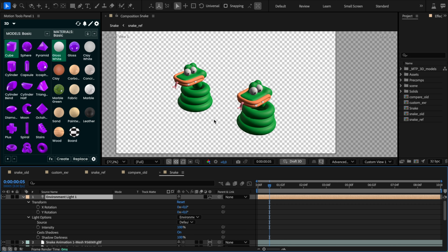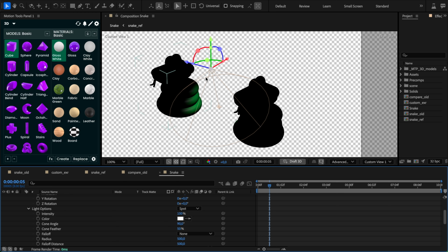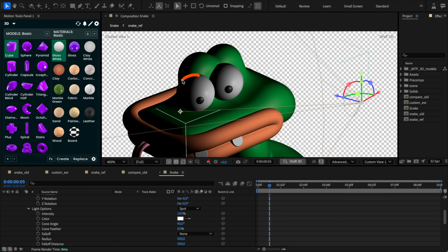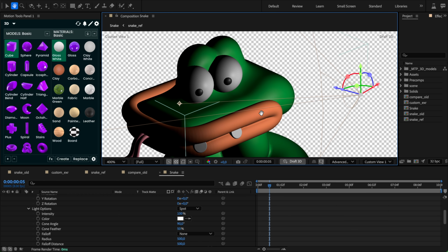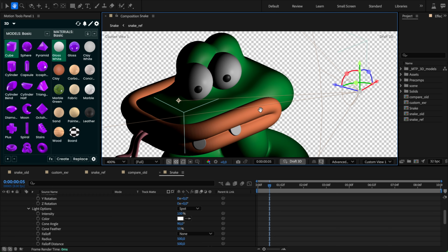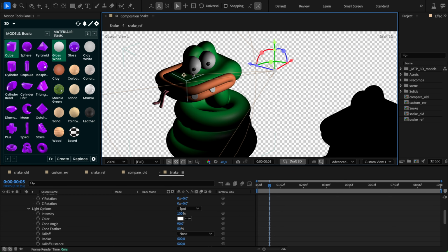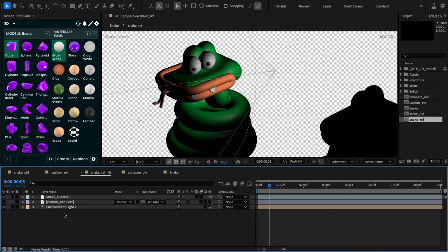You can notice that with our previous lights, we don't have realistic shadows. You just see how meshes self-shadow. In other words, the shadows are located only on separate parts and don't interact with each other. This is the limitation of the simple lights in the advanced 3D engine and imported 3D models. They will work in the classic 3D engine, but you can't use imported models in it. So, the environment light comes into play, which creates realistic rendering.